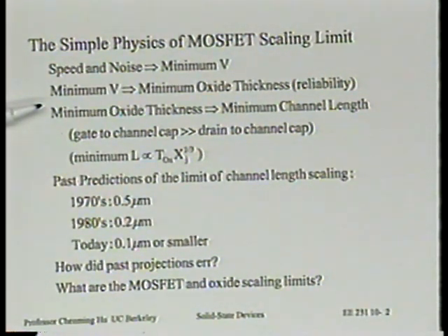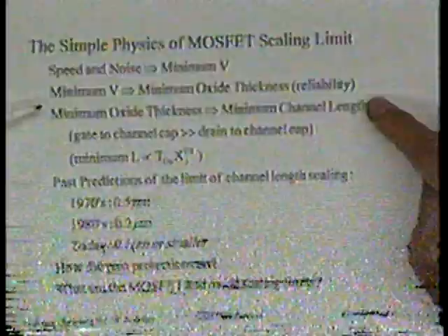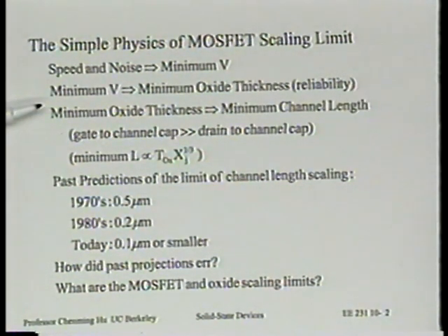And why couldn't people find out very easily? Well, we'll talk about that as another topic later in the course. In fact, that would be the last topic we'll discuss, thin oxide. The hint is that reliability is a very difficult problem to deal with. You have to guarantee it's reliable for 10 years. We don't have 10 years to do that testing. So how do you figure out how thin an oxide is acceptable? It's very difficult.